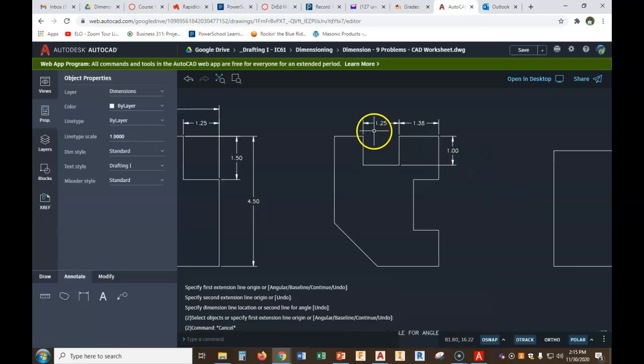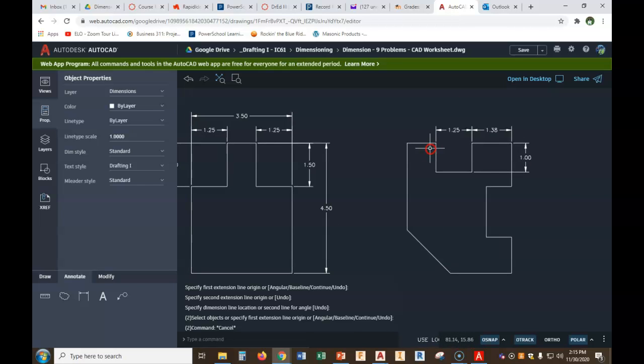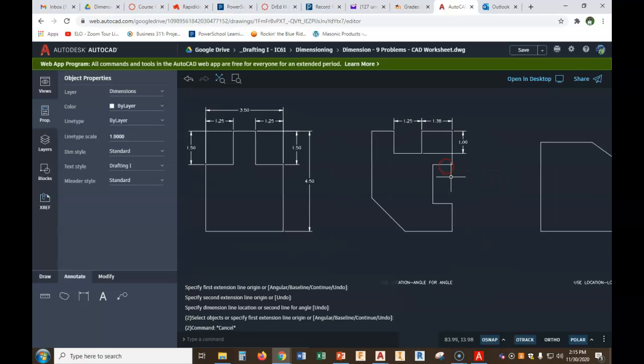So look, this feature, location, size. Remember, always location left to right, location top to bottom, size. Sometimes we can do it all in 2 dimensions. On some things, we can actually do it in 1 dimension. We'll get to that in a minute. Okay? So how about this cutout?